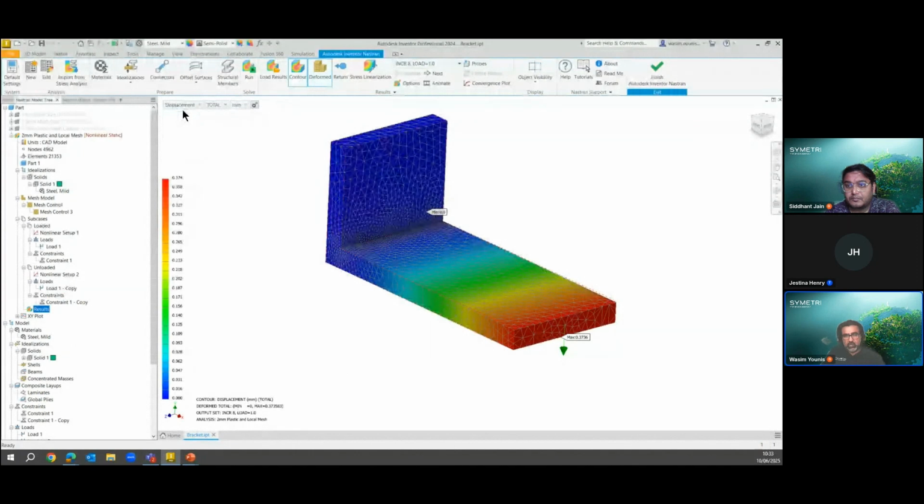That's the displacement value, and you can't tell whether that is permanent deformation, or a deformation applied by the load, or is it a vibration, or whatever it is. But typically, I'm going to assume that's the deformation. But then if I go into my second final subcase here, now what you are looking at is going to be permanent deformation. And this is in millimeters, everyone. So what you can see there, there's no permanent deformation. So that's a good sign. So when you put the load onto there, you know for sure that there's no permanent deformation.